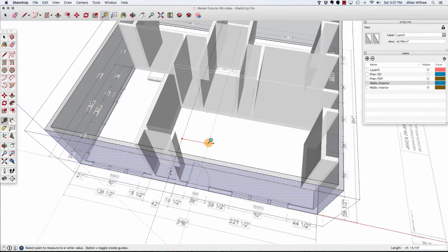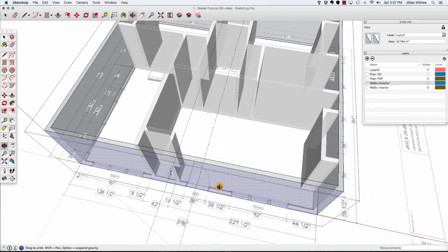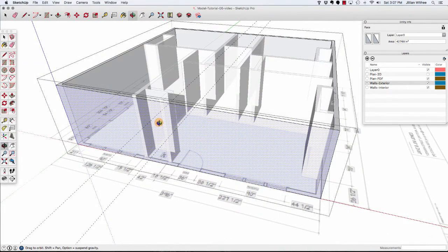And then we'll drag over again 36 inches. And those are the 2 edges of my front door. And now click on a vertical edge of that same wall, and you can drag it over and snap it to one of those horizontal guides and do the same thing for the other side.